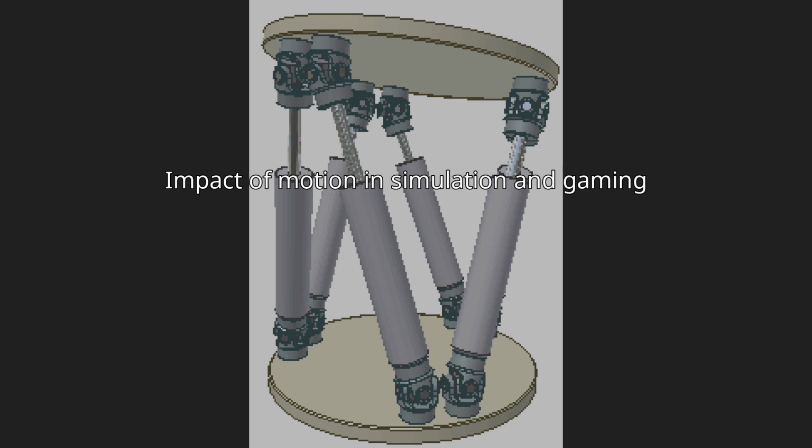In other words, motion-enabled gaming is more realistic, thus more iterative and more stimulating. However, there are adverse effects to the use of motion in simulation that can take away from the primary purpose of using the simulator in the first place, such as motion sickness. For instance, there have been reports of military pilots throwing off their vestibular system because of moving their heads around in the simulator, similar to how they would in an actual aircraft. However, due to the limits on simulator acceleration, this effect becomes detrimental when transitioning back to a real aircraft.